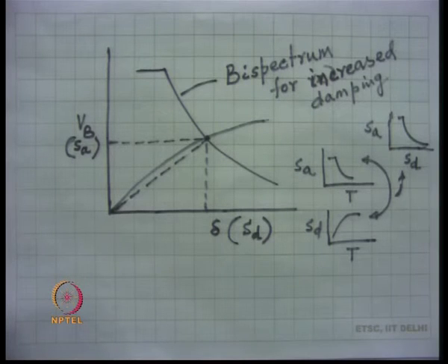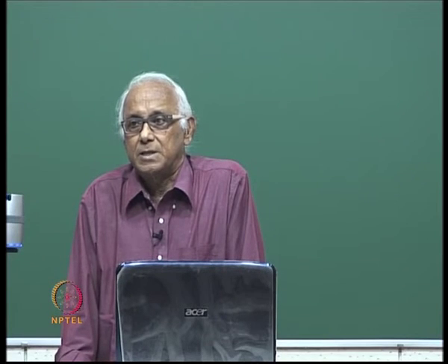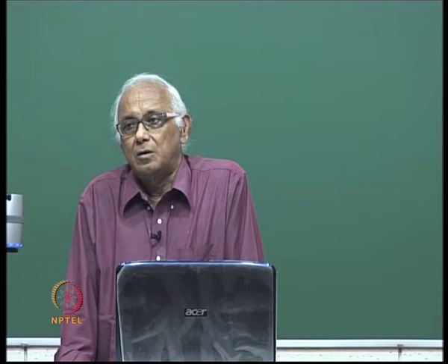The first thing is that one can see the different states of the system after the yielding, that is, how the plastic hinges are forming at different cross sections, and what the nature of those plastic hinges is, whether at the plastic hinges the rotational capacity has been exceeded or not, and the plastic hinges where still some rotation can take place.